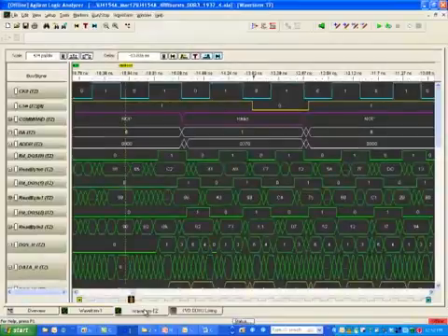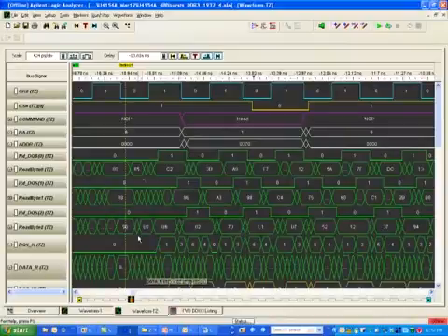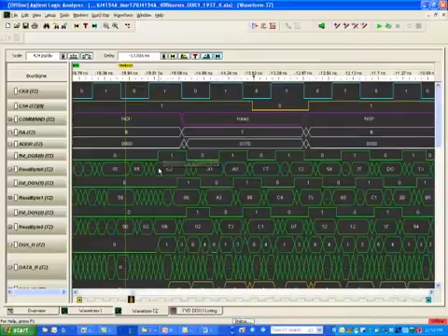Moving to the timing zoom window, here we have a high-resolution capture of all signals on the bus. Of particular interest would be each strobe with its associated data byte, where we can observe the flyby routing.